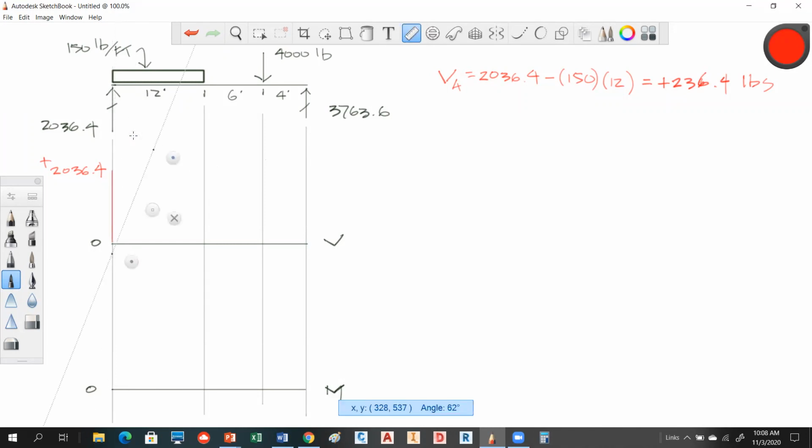Okay, so what that's saying is this is diagonally dropping from that point down to, let's say, a point about right there, like that. So notice what's happening as we step across this beam, the shear is diminishing. It's getting towards zero, all right? But it's not going to zero, so we don't have a point of maximum moment anywhere yet, okay? Make sense? Yep. So at this point, what's happening between the end of that loading and this concentrated load? Is there any force in there?